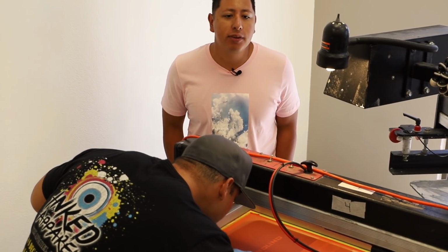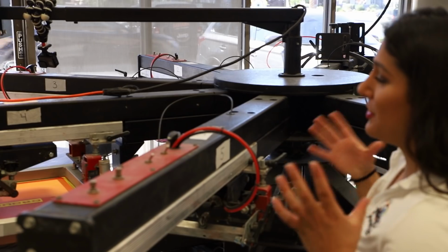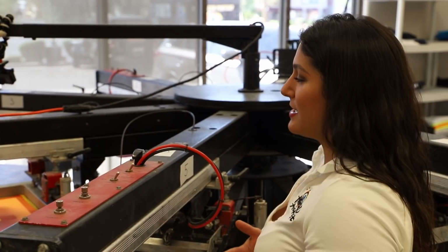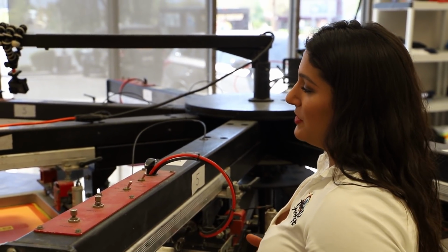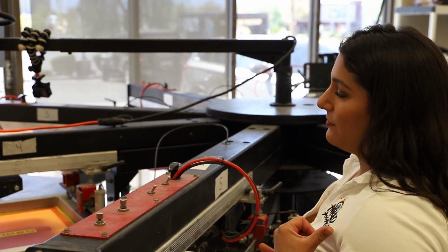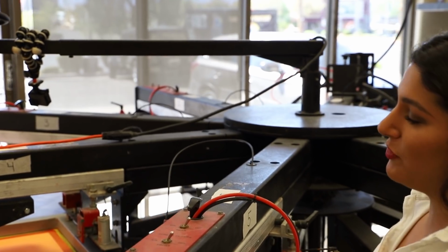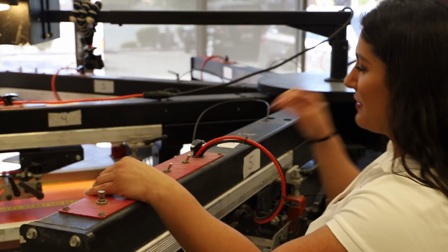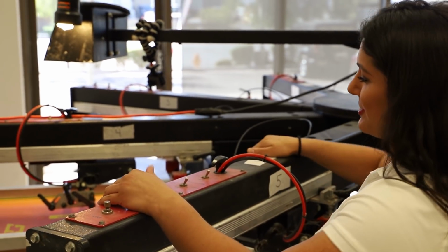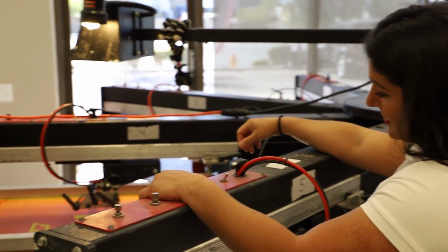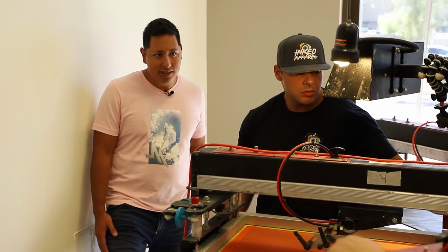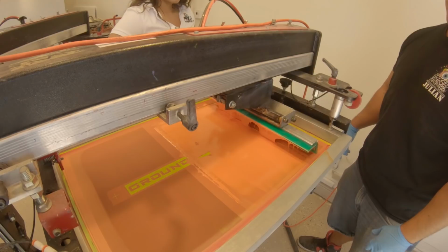What's been a learning curve with screen printing so far? You have to be able to look at a design and know what colors you want to print first. That was a learning curve for us. In the beginning, we used the heat press, and for certain brands of inks, if you put too much pressure, it's just gonna spread the ink. Just when you think you got it, another thing happens. So there's definitely a learning curve in screen printing, though not so much as DTG for sure. We're already kind of rock and rolling with this, but still a learning curve.